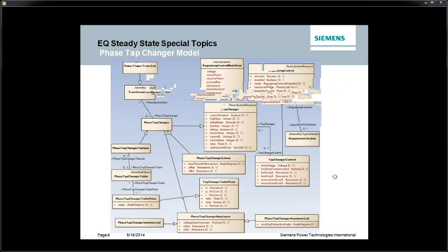You find this on your transformer test report or your nameplate, and this is used to convert the impedances from engineering units to per unit. So it's very important that that gets classified properly. On the tap changer, each tap changer is defined a neutral U, and this is the voltage at the neutral tap point. So with your tap changers, you define a high step and a low step and a neutral step. A neutral step is considered to be at neutral voltage.